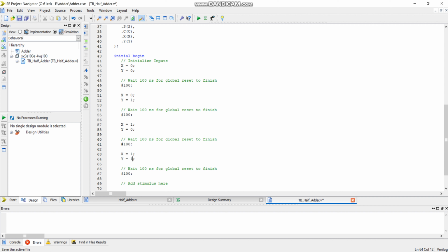So first click on the save button, right? And then click on this half adder. You will again see this LSIM simulator. You click on the behavioral check. Now once you have done that, you see this green symbol, now you can move to see its output.